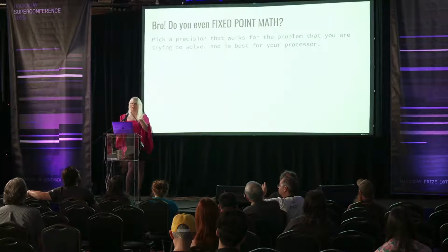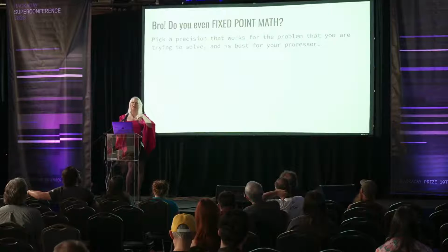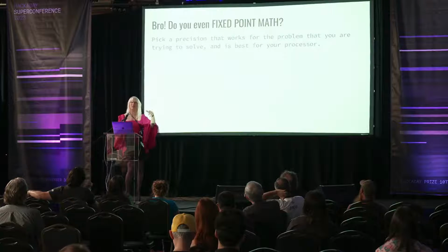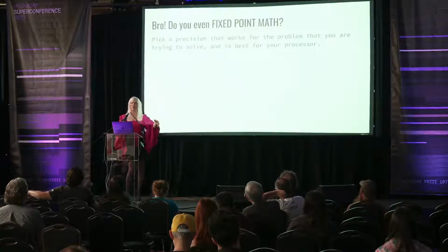So pick a precision that works for the problem you're trying to solve. Every problem that you're doing, it's not like you just say, oh, I turn on fixed point math and it does the thing. No, pick a precision that works with what you're doing. If it only goes from 0 to 1, then use all of your bits for your fixed point math.